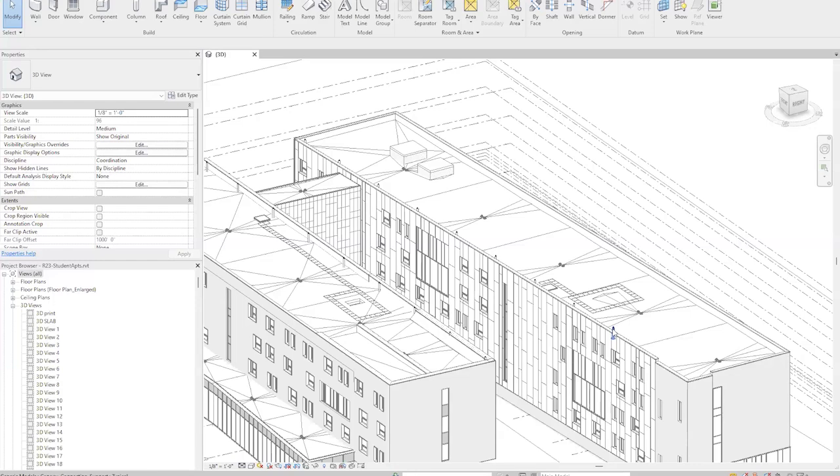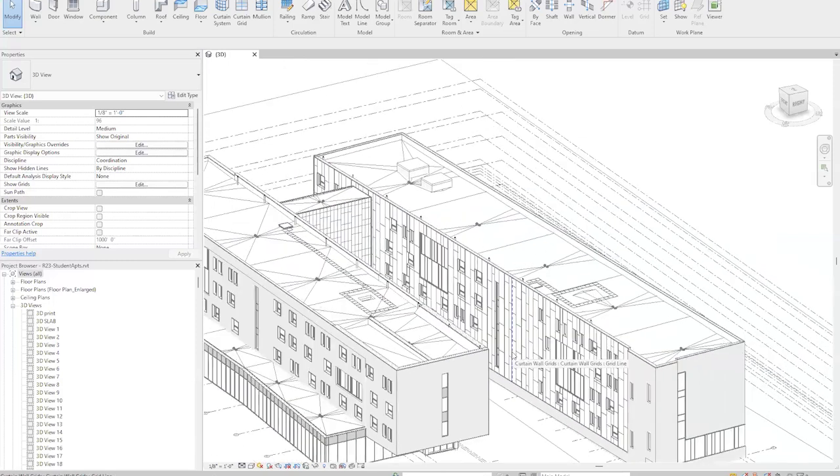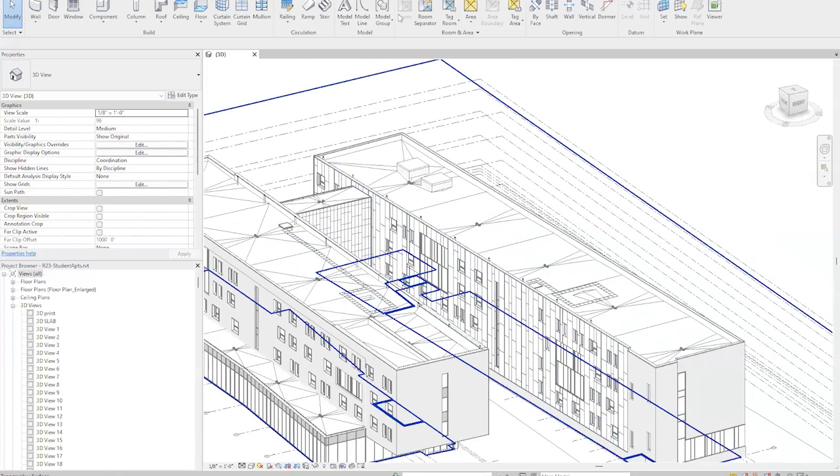Depending on what you're doing, sometimes you're going to be going from Rhino to Revit. In this case, we're pretty much just using Grasshopper to generate Revit geometry. In other cases, you're going to go from Revit to Rhino, maybe the fabricator or doing some sort of analysis.